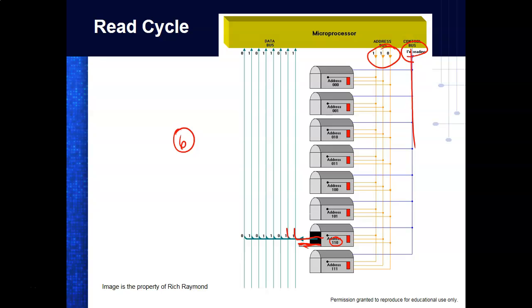It's pretty interesting. So hopefully that explains the address bus and data bus. The bigger the address bus, the more things you can select. The bigger the data bus, the bigger communication we have. And usually that's what they're doing when they define a processor, is they're saying, what are we communicating? And so a 64-bit processor means that the data bus has got to be at least 64 bits.